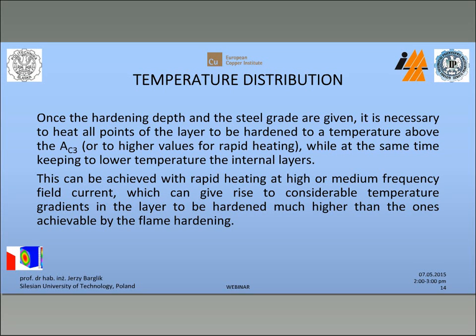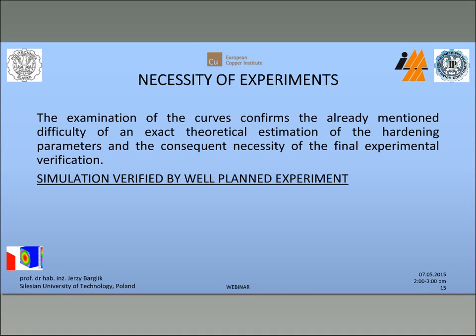This can be achieved with rapid heating and high or medium frequency field current. Low frequencies are not applied for this purpose, of course, because of too big a depth of electromagnetic field penetration. So it is only medium or high frequencies of field current. And of course, simulations are very good. We could consider many cases, many practical examples, but of course simulation should be verified by well-planned experiments.